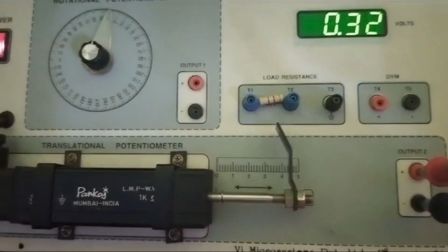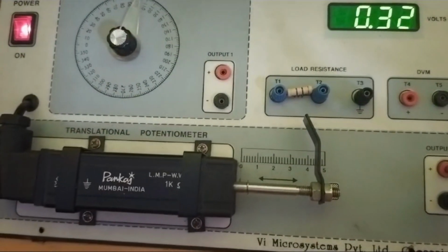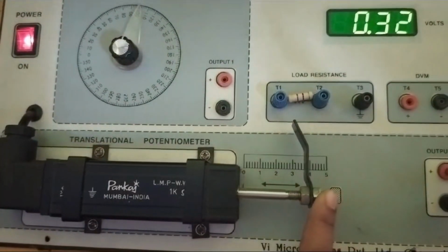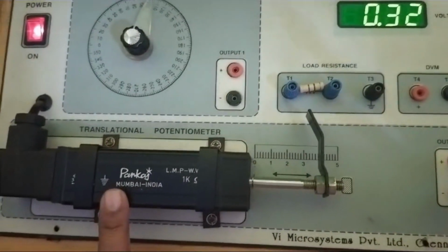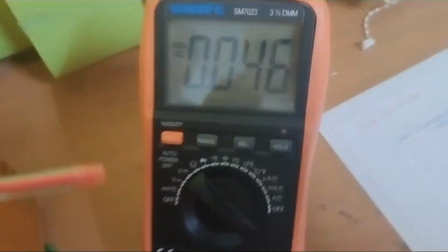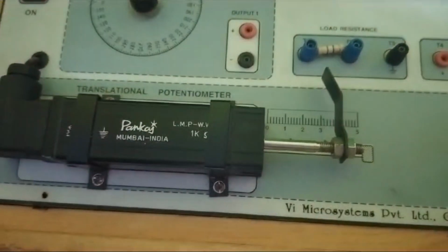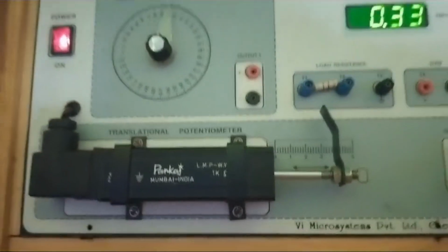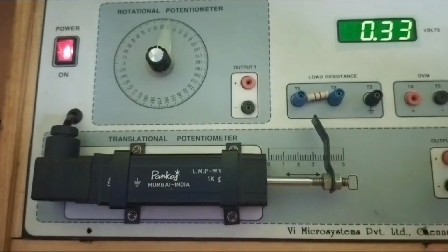Here, it is to be observed that the potentiometer doesn't convert the resistance directly into the voltage. The input is the displacement, which is provided with the help of the shaft. This shaft will change the resistance. In turn, the resistance is converted into the output voltage. The output voltage can be measured with the help of the multimeter, and it should be in the DC condition. This potentiometer is also called a passive transducer, which means for this operation I have to provide an external power source to the potentiometer.